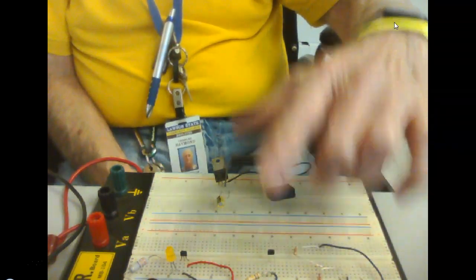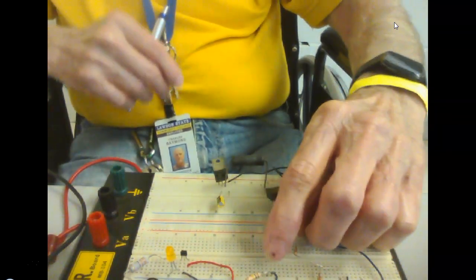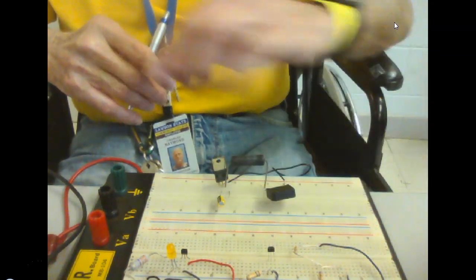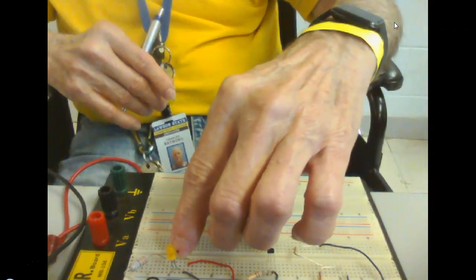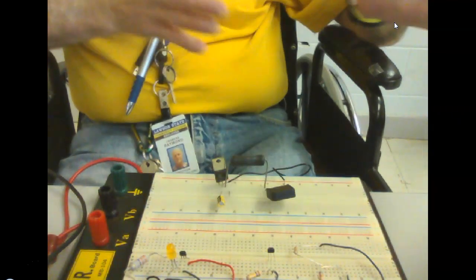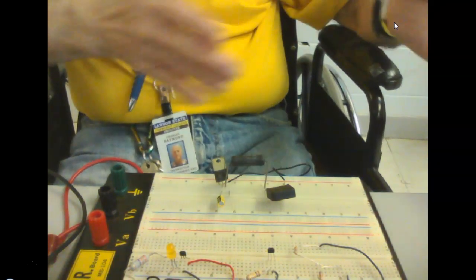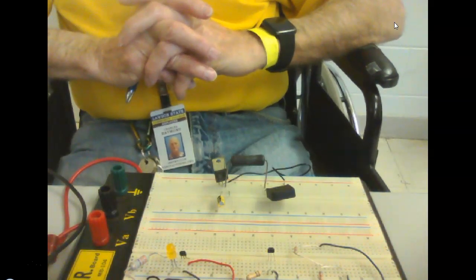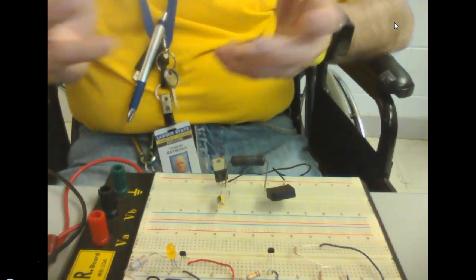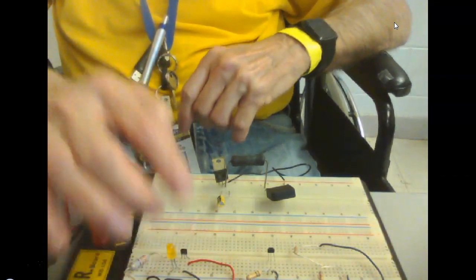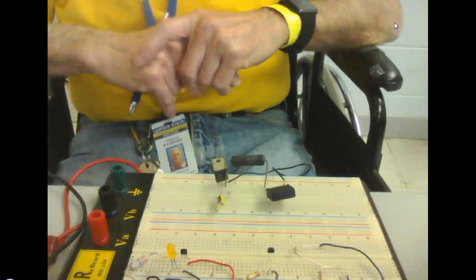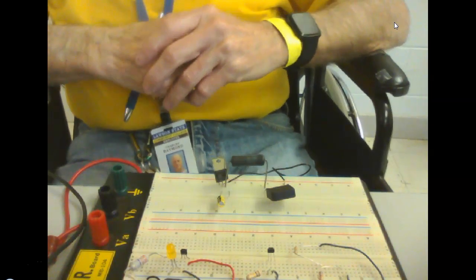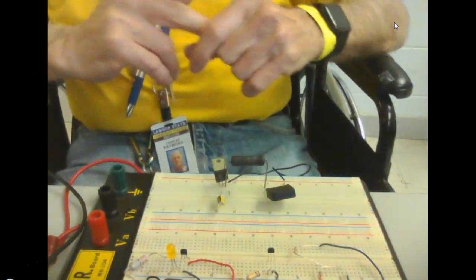Like I said, this over here is a linear, which would be what's in a clamp-on ammeter that has the ability to sense DC. It would have one of these. These will be what we have on our cylinders that comes on when it's in position and goes off when it's out of position. So, very simple 3-wire sensors, and you won't see the actual sensor itself. It'll be encapsulated in a piece of plastic or something to make it more suitable for industrial applications. We don't have any magnetic reed switches.